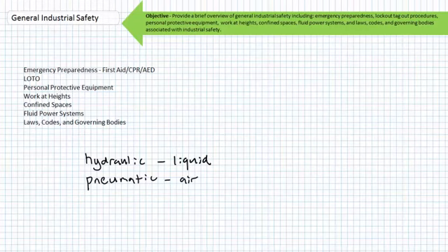The principal operational difference between the two types of systems, besides the phase of the fluid medium, is that of actuation speed. A hydraulic cylinder extends continually as incompressible fluid fills the actuator. A pneumatic cylinder has a tendency to rapidly pop into position only after a certain actuation force has been achieved. Be aware of this if working on a pneumatic system and don't get popped.